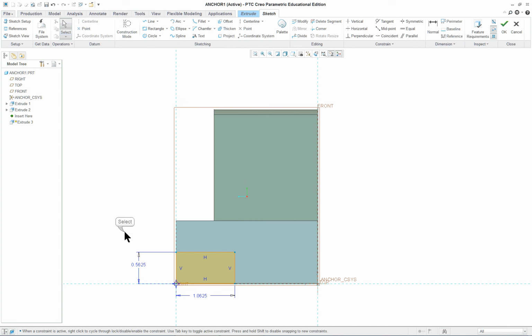You can change them in the model when it's completed. You can alter them to anything you want at any stage in the design process, as long as the dimensioning scheme is correct. If you had a dimension from here to here, then you could not alter this size correctly. You'd not be able to do an ECO on it. Therefore, you'd have to go back to this sketch, put this dimension in so that it's available when downstream you have changes in your design.